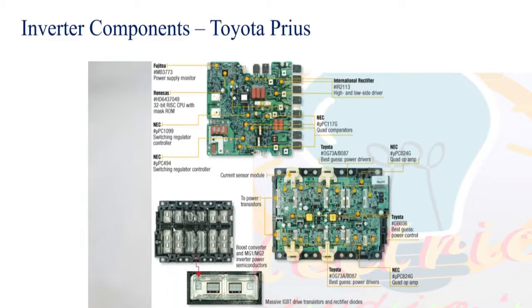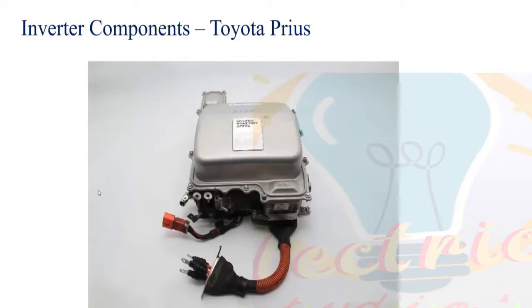The main component is your power switching device, so I have to size the IGBT rightly for the right application. If your electric vehicle is demanding very high torque, then obviously the switches we are using should be able to withstand higher current capability, right? Because when I put high current, the temperature of the IGBTs, the switching devices, will increase, which in turn will damage your performance. So you need to be very careful when selecting and sizing the power devices.